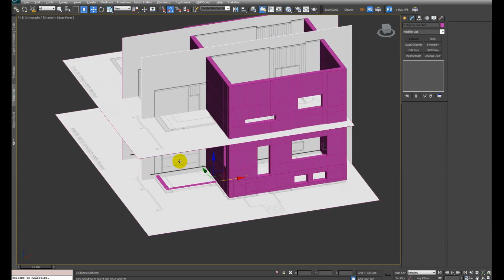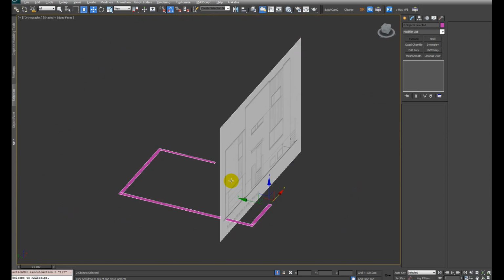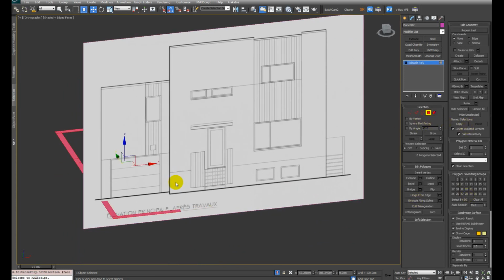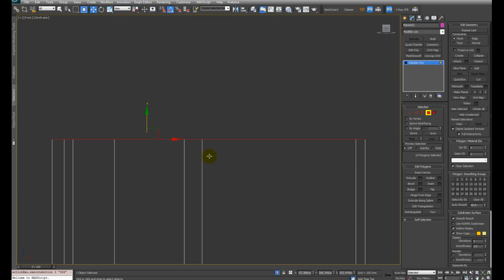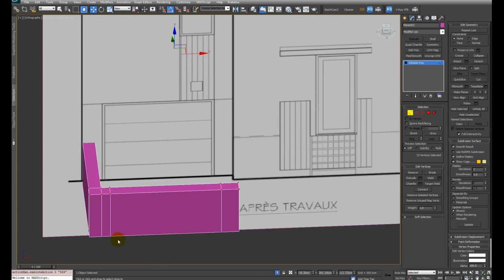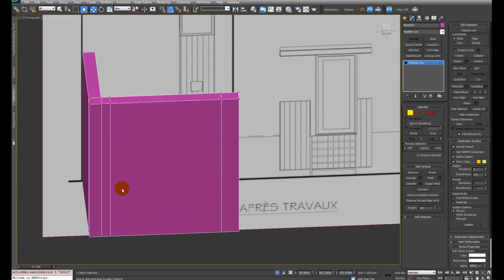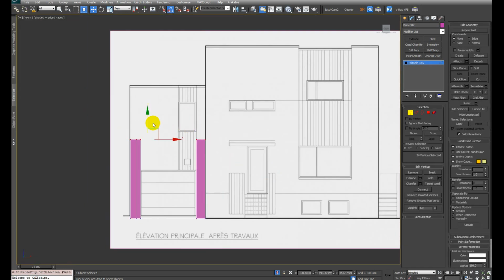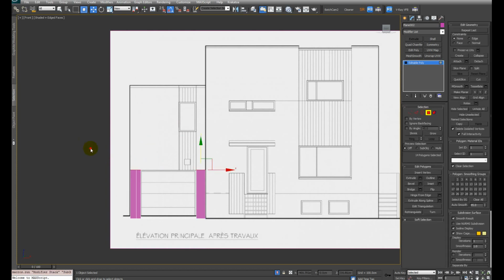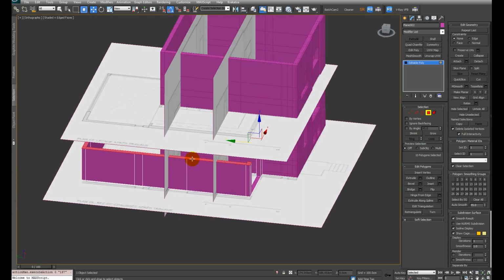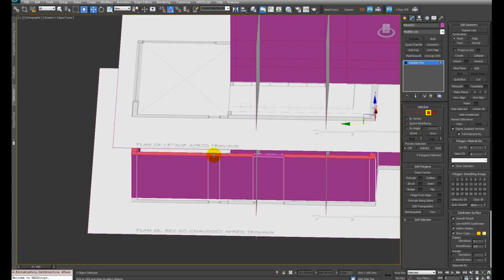Let's select this geometry and the front plane. So with this selected, go into the polygon mode, select all the polygons and hit extrude. Go into the front view and let's see what we've got here. Okay, so actually with this area we don't need to extrude it, so let's hit Ctrl Z to get back and deselect that area. Great. Let's bring back the other planes and let's see this area we don't need to extrude.